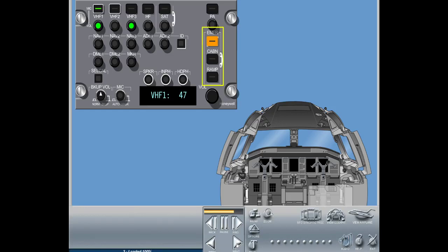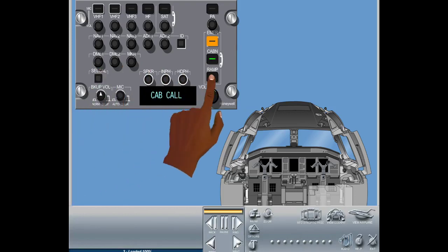The telephony buttons on the right, emergency, ramp, cabin, are set up with a hot mic which provides interphone communication on a telephony basis. A light illuminates inside the button to indicate that it is pressed. More than one telephony button can be selected at a time. The audio selection button above the display enables each crew member to listen on either the speaker, interphone, headphone, or passenger address. A light illuminates inside the button to indicate that it is pressed. More than one selection is possible.